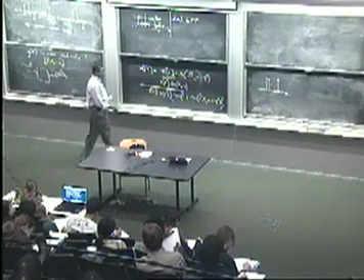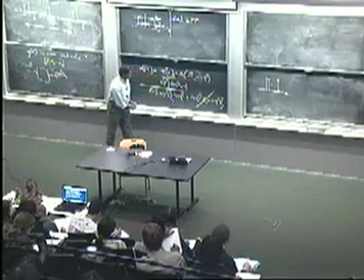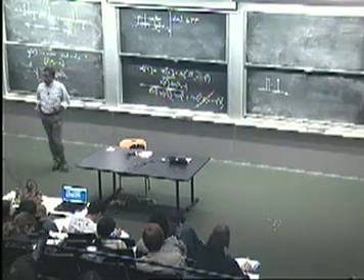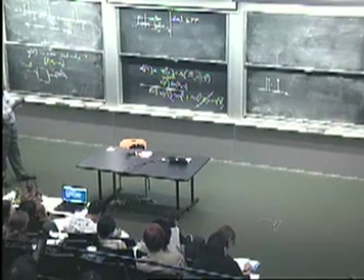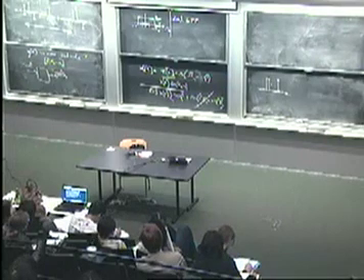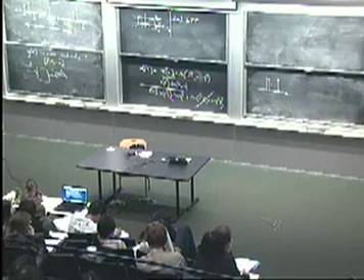You're going to do some filtering to get rid of this piece, the double frequency piece, and pull out just what you're interested in, except now it's no longer x of n itself. It's x of n multiplied by this cosine. So can you see that this could lead you into trouble? What's the worst case here?